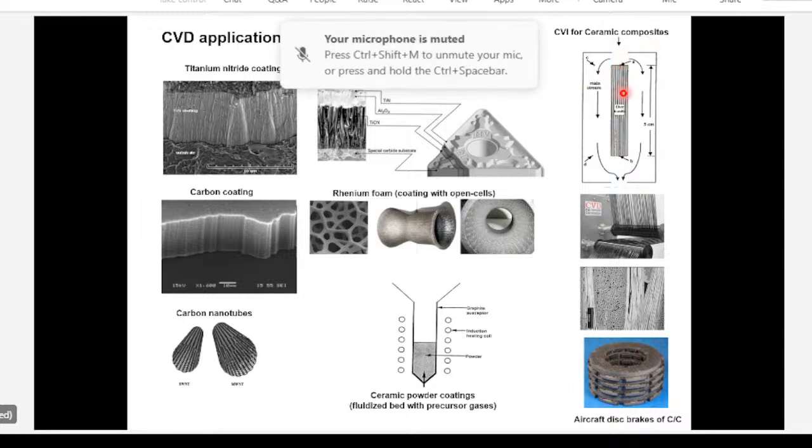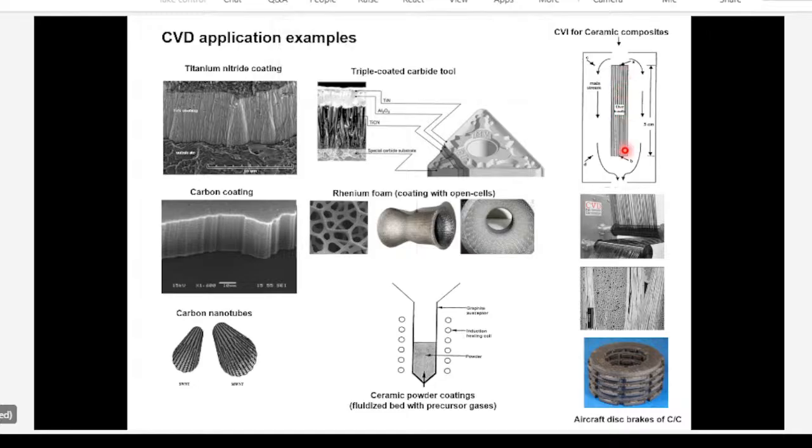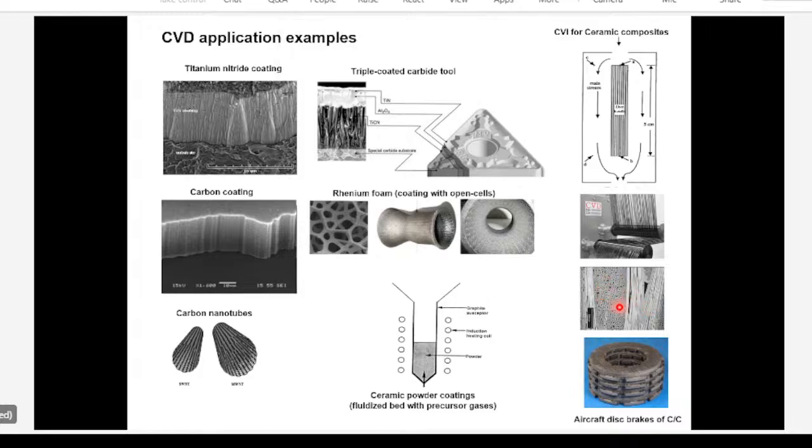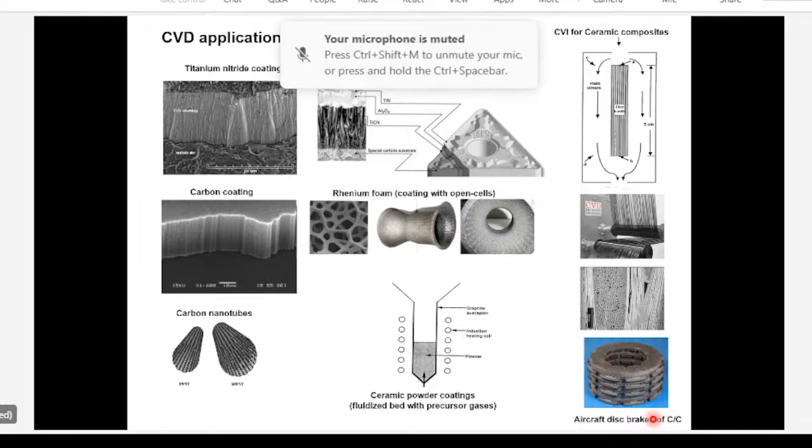As they flow through, they react with one another and deposit carbon between the carbon fibers. So with time, you create a carbon-carbon composite that has carbon fibers inside and amorphous carbon deposited in the fiber. That composite is used to make brake discs and several other components. So these are some applications of the CVD process.